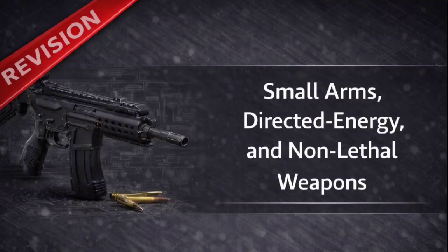Okay, so blowback is limited by that heavy unlocked breech. For high-powered service rifles and machine guns, we have to move to systems where the breech is firmly locked during that high-pressure phase. Let's start with recoil operation. How does the principle here fundamentally differ from blowback? The core difference is the lock and the movement of the barrel. In recoil operation, the barrel is mounted as a free fit inside the weapon body, and the breech block is firmly locked to the barrel during firing.